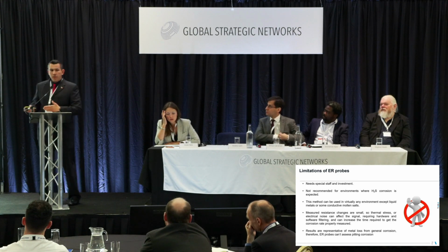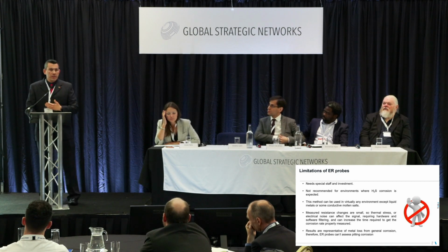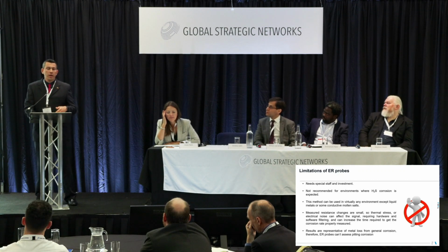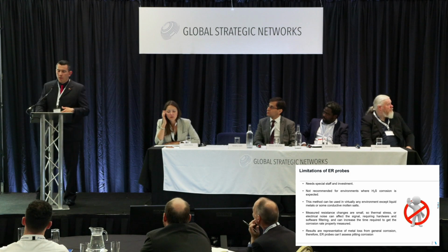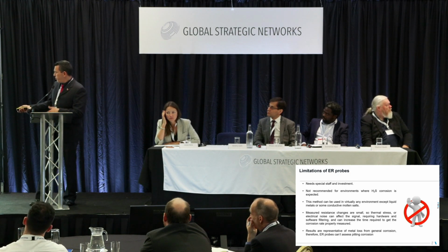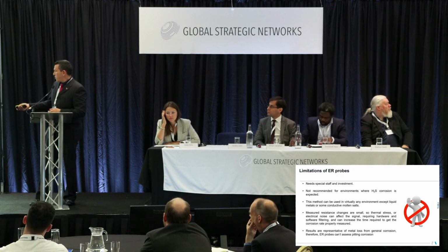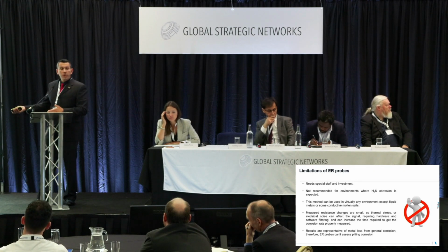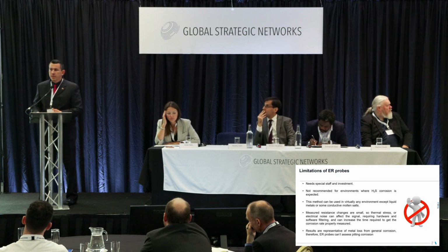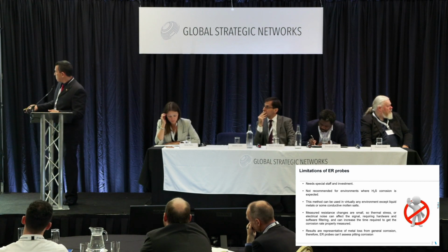And as I said already at the beginning, this technique can be used mainly for uniform corrosion and velocity influenced degradation processes, because you can't assess pitting, for example. MIC, microbially induced corrosion, you can't assess that one with corrosion probes.